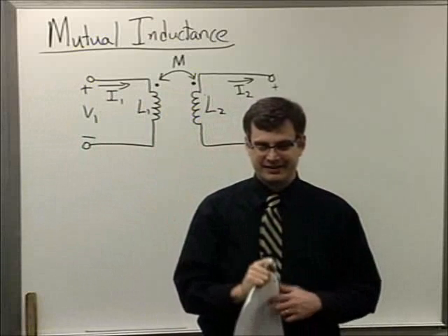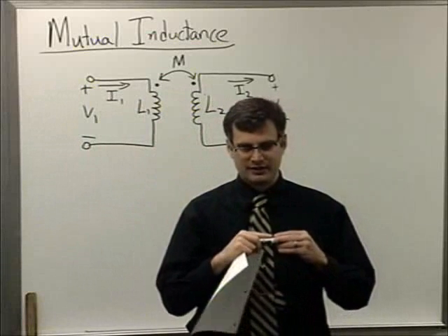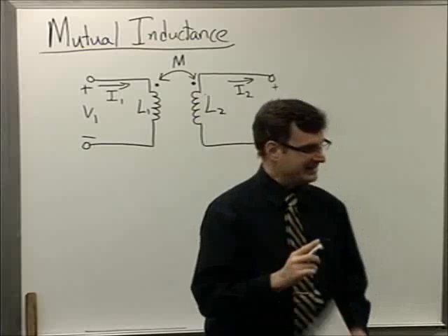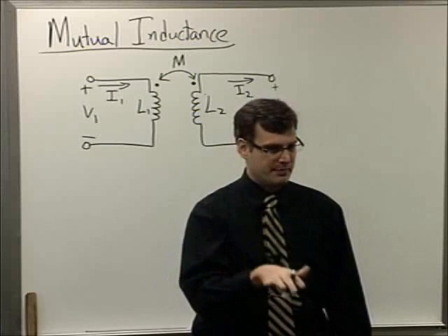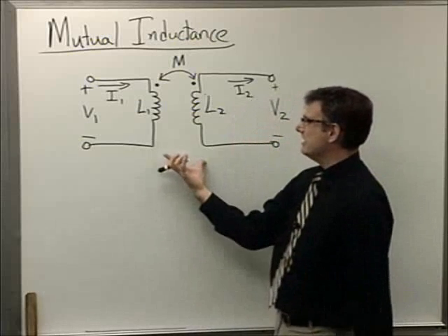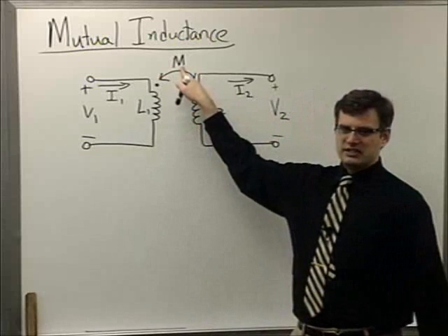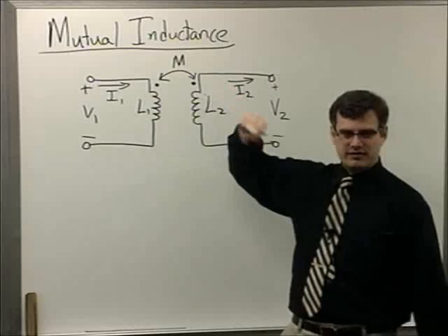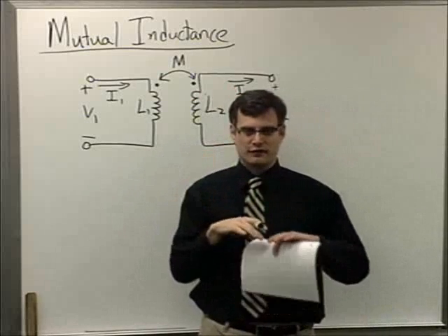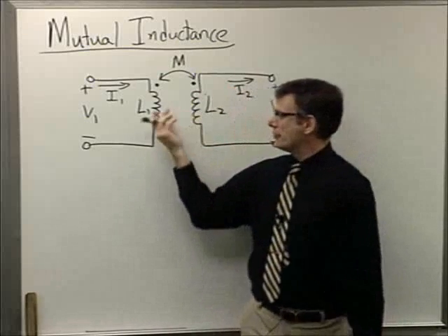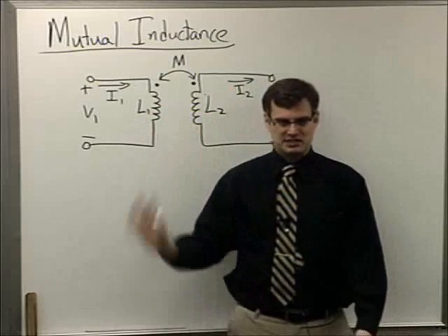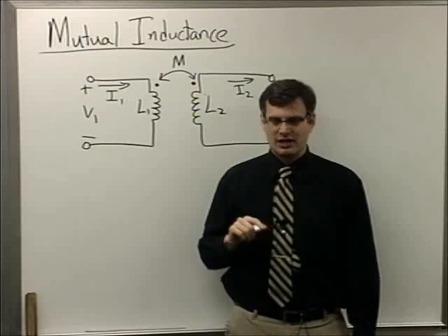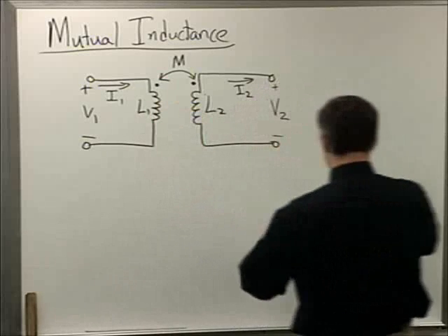Yeah. So is that kind of like a transformer, but it's got no core going to it? Yeah, exactly. A transformer in power engineering, if anybody's taken the power engineering class, is exactly this thing. The only difference is that M has a specific value. Usually in power, you don't want any what's called flux leakage. You want 100% of this flux to be shared with this flux. And that minimizes losses and maximizes power transfer. And so M takes a specific value in there.